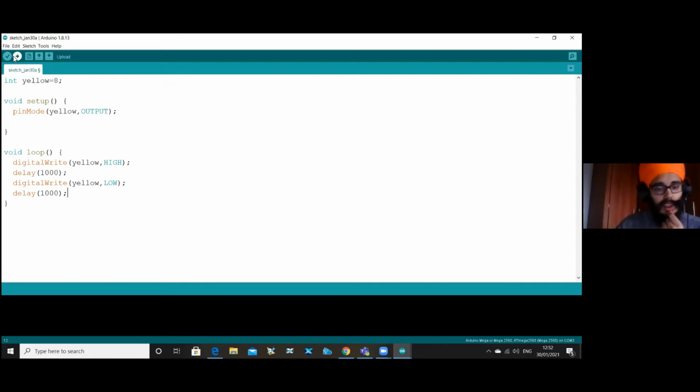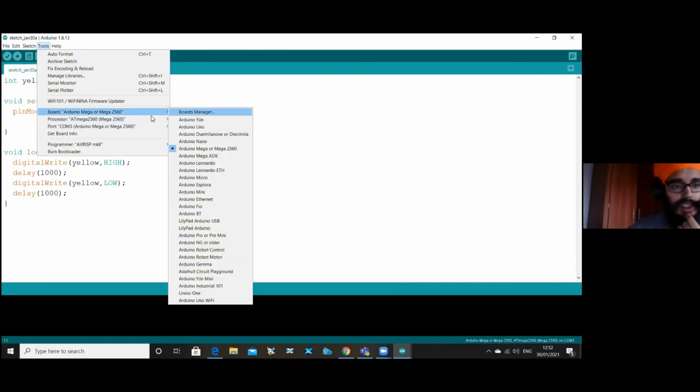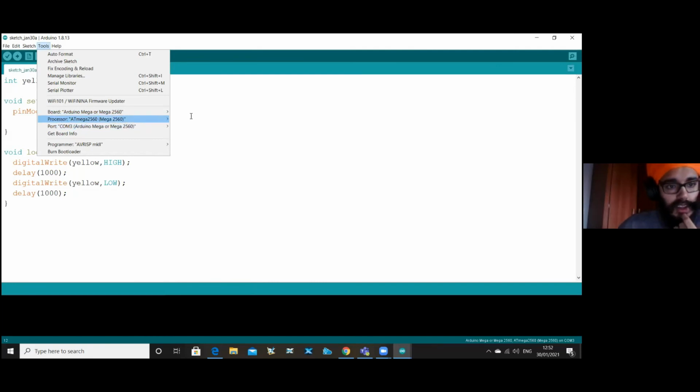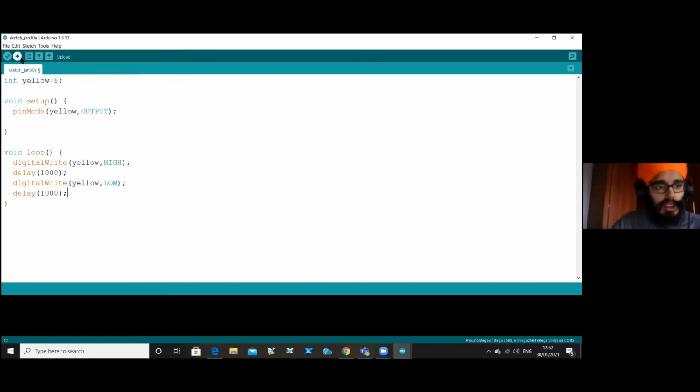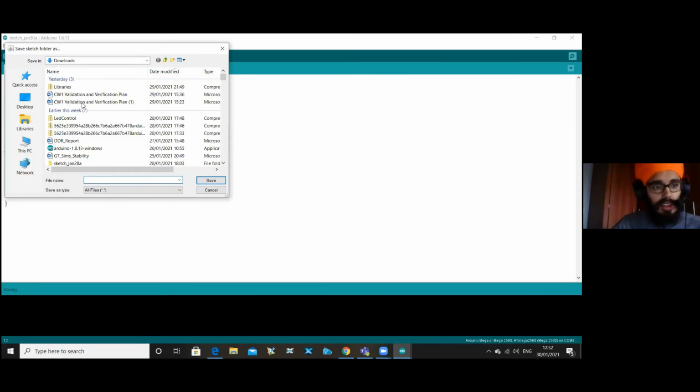So upload that. First of all, the first thing you do is set the port and the board you are using. So you go to tools. Okay, the port is set. Try verifying. If you just want to upload, you can hit the upload button. The upload does the verification and uploading at the same time.